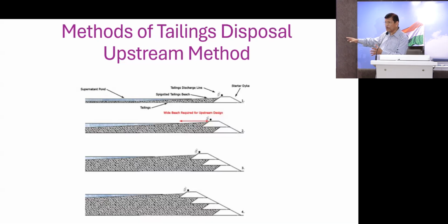But that dam we normally design from the tailings, taking the sand part of it. So we took that sand part to build the next one. But again, the next one is going over the same tailings material. So for the second structure, what is the foundation?